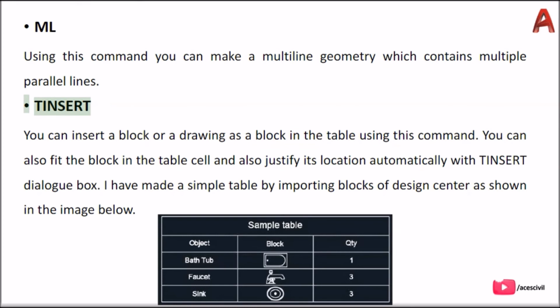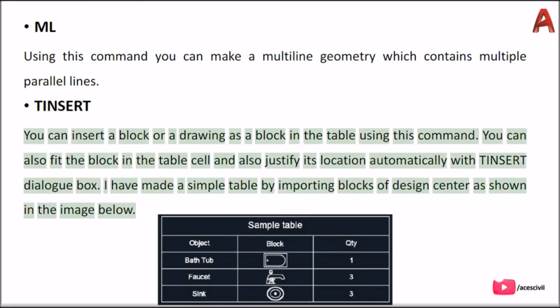Insert. You can insert a block or a drawing as a block in the table using this command. You can also fit the block in the table cell and also justify its location automatically with the Insert dialog box. I have made a simple table by importing blocks of Design Center as shown in the image below.